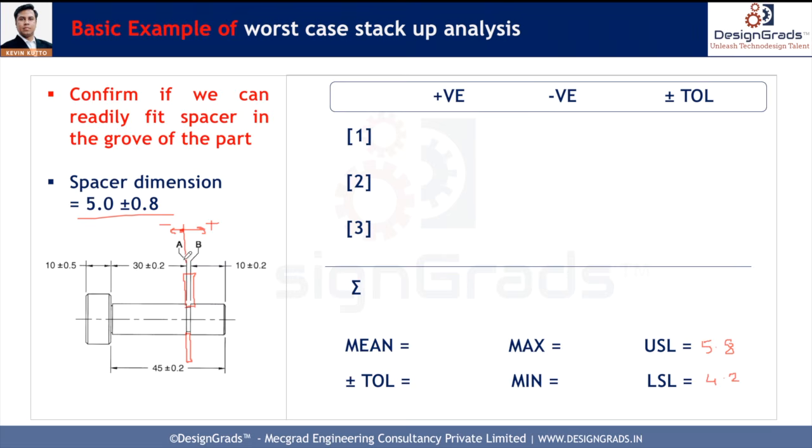Now the second thing we have to do is find the chain. What is a chain? A chain is the shortest chain from the start point towards the end point. This chain will be a chain of dimensions. Now what is the criteria? In a chain, when our first dimension ends, the second dimension should start exactly from that point, and it should create the shorter distance.